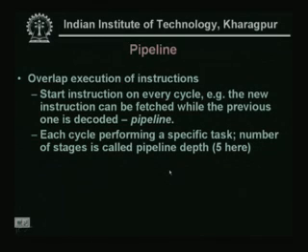Now, another very unique and very important concept has come into the picture: the pipeline concept. The concept is the overlapping execution of instructions, and the utilization of overlapped execution of instructions is called pipelining. The idea is that on every cycle a new instruction can be fetched while the previous one is being decoded.